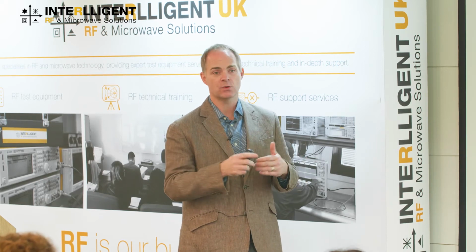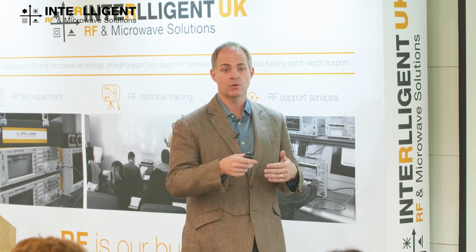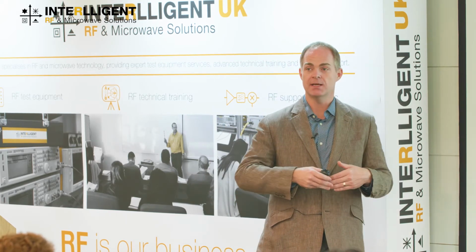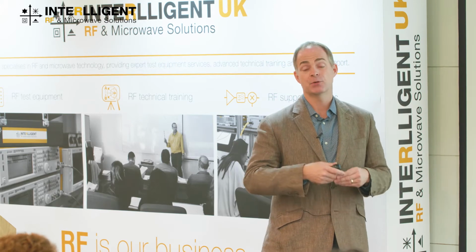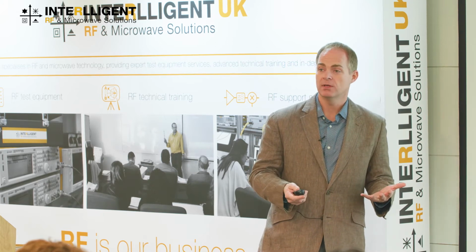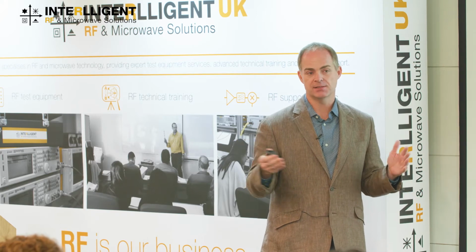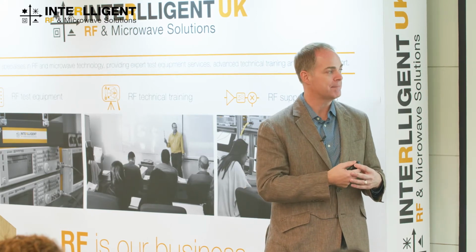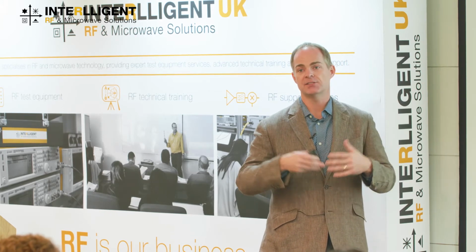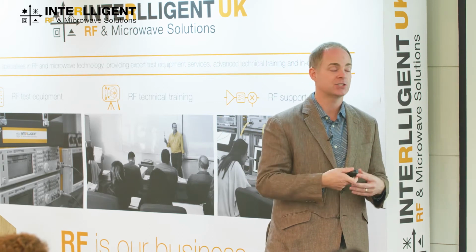As you move to higher frequencies, where we're starting to talk about needing gigahertz of bandwidth, or even more so if you move away from communications and you're moving into an EW application or something where you need decades of bandwidth, being able to achieve sufficient efficiency in the amplifier so that you can get rid of the thermal issue becomes more and more critical. And being able to actually match those devices is easier when you have a wide band gap transistor that allows you to have a higher output impedance, because as you scale it up and you shrink down that output impedance, it's still high enough that you can match to it properly.